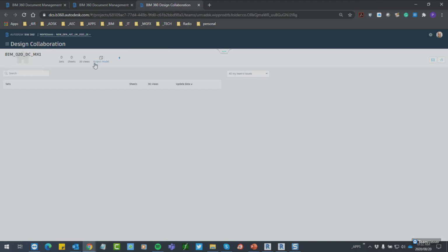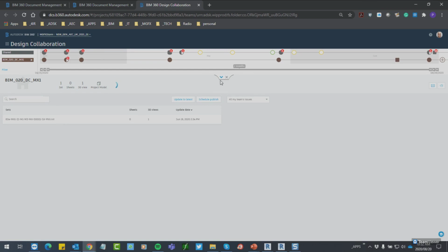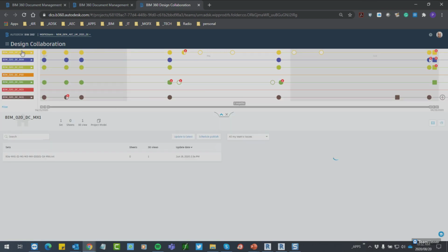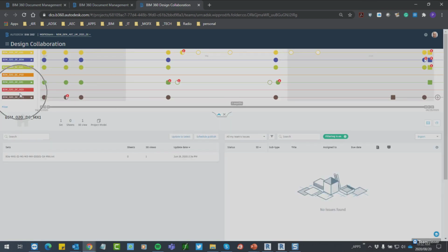If it is new to you, this is a way in which the different disciplines share their files with each other. So there's a timeline with the different disciplines, and at specific instances they share packages with each other. And once the package has been shared, somebody else will consume that package. To put it in simpler terms, the BIM manager from the architect, AX1, shares their package, and then after that, the BIM manager from the mechanical company accepts that package.